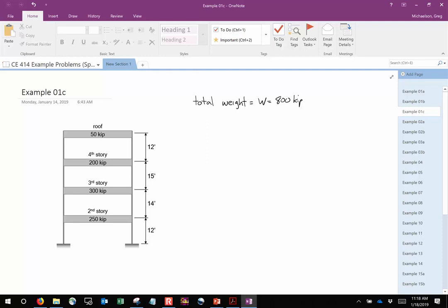I mean, think about it like this. That column, let's say it's a W10 by 49. That's 49 pounds per foot. Now let me say this: that's not always the case, and in some structures, that can be pretty heavy. Usually what I would do is account for everything and then just lump it. But it just depends on your structure. Sometimes it matters, sometimes it doesn't. But I would say more often than not, I would just count everything.